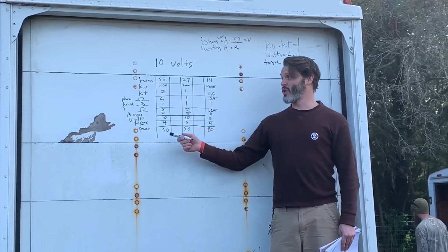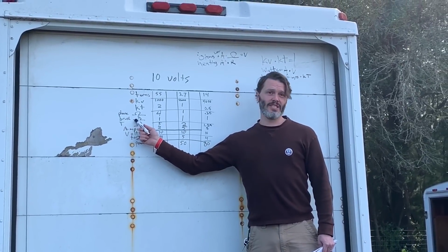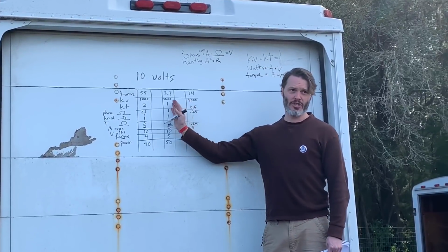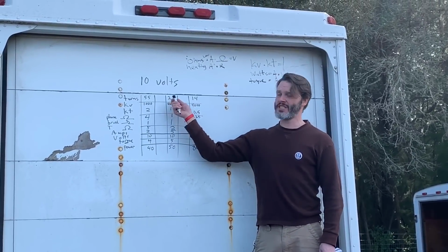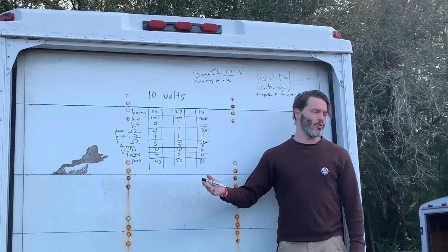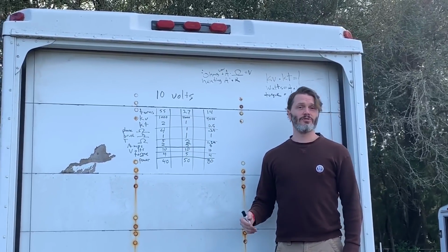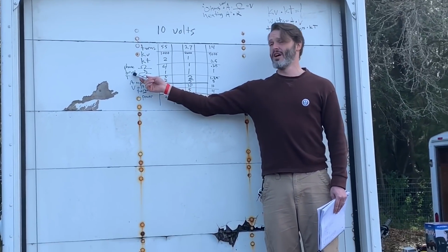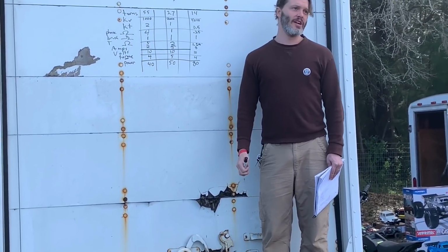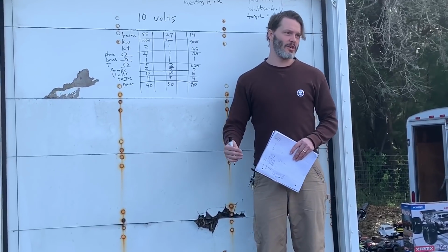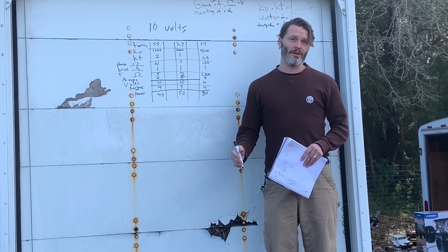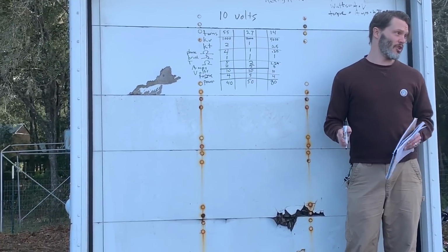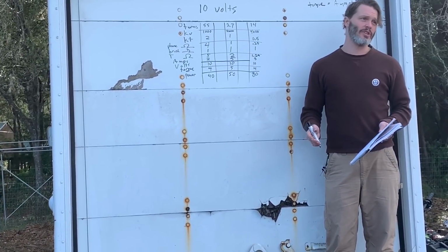And alternatively, what if we reduced our brush resistance? If we went to say silver brushes versus copper brushes, now this formula is going to change a little bit. Everything is going to shift over, and instead of the 27 turn being in our magic zone, maybe it's a 25 turn. Well, the same thing for going to a hand wound from machine wound. As much as we can reduce the resistance of that brush and commutator interface, we can actually bump the speed up just a little bit. Now it's not a whole lot. Most people may not notice the difference on there. Of course, going from machine wound to a hand wound is a huge difference in there. Pretty much twice the torque that you can pull out of it.